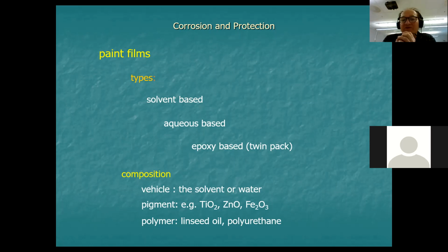So the epoxy-based paints cure quite hard, it has to be said. And they are very, very durable, far more durable than the other two types of paints I just mentioned. But they are very expensive. So you generally use these on applications which only need that extra durability. For example, painting the hull of a large ship might well use epoxy-based paints, or something that's exposed to an aggressive environment.